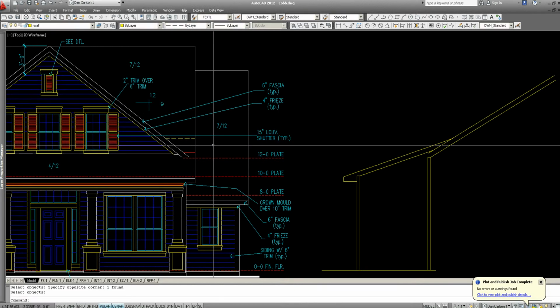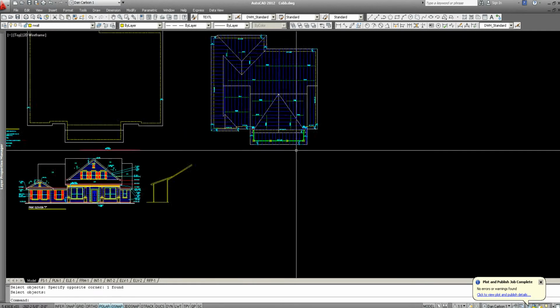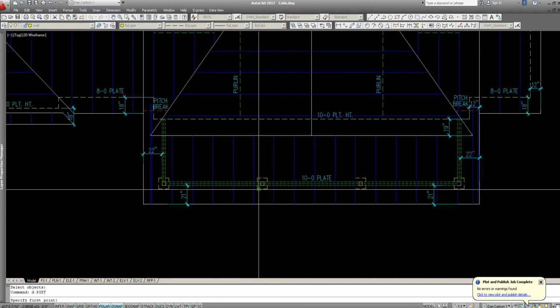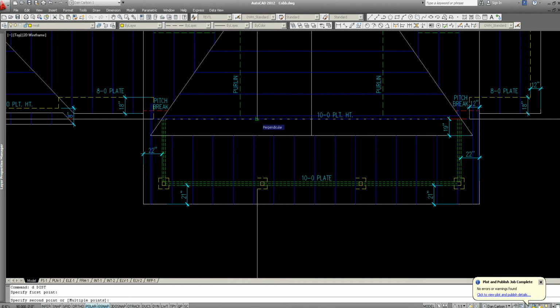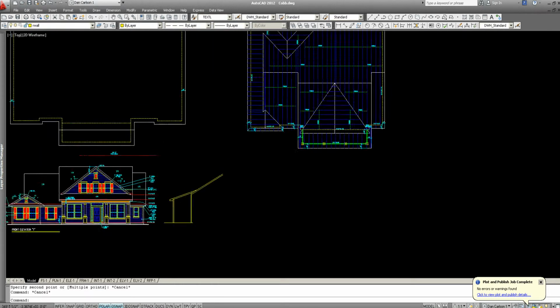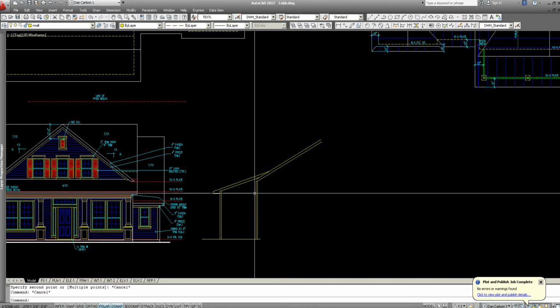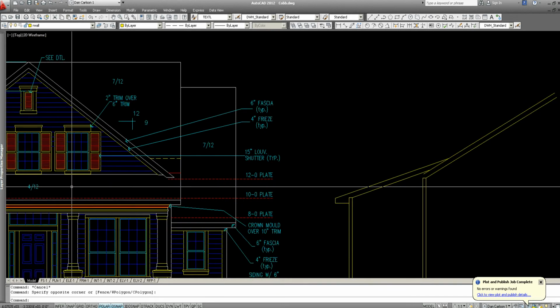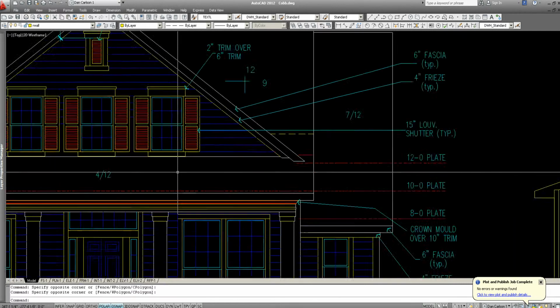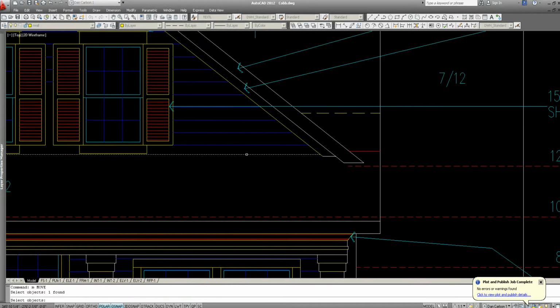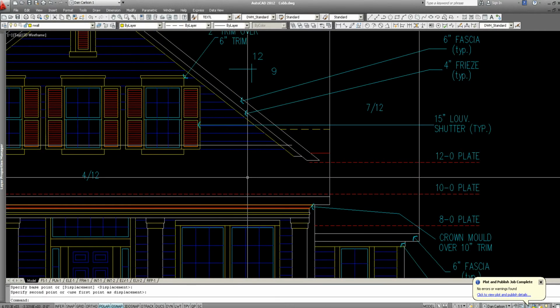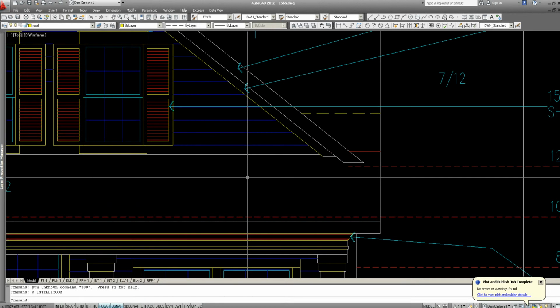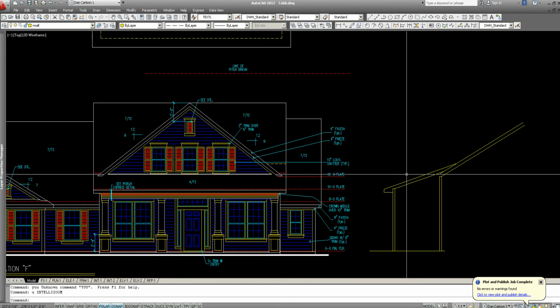And that might be because the original plan, the base plan, had this wall. This was only a 6-foot 6-inch deep porch, and these buyers have changed it to an 8-foot deep porch. Unfortunately, that's going to cause a problem with this roof here cutting up into these windows. It's going to look kind of like this. So what we might need to do is make an executive decision and change that to a 3-and-12 pitch roof.